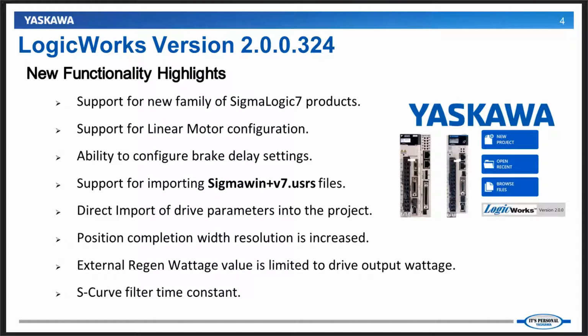You can directly import drive parameters into your project. Position completion resolution has been increased to 6 decimal places. External regeneration wattage value is limited to drive output wattage now. And you can also configure the S-curve filter time constant through Logicworks for smoother acceleration and deceleration profiles. Of course, I will give a brief description of each of these topics later on in this video.